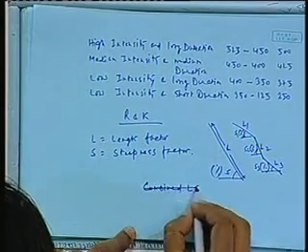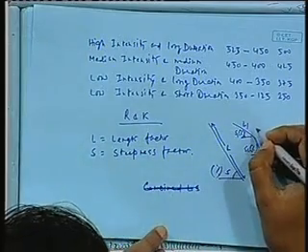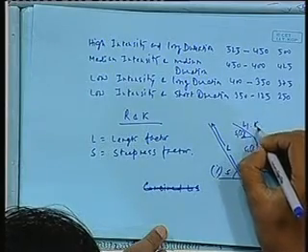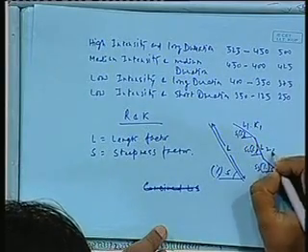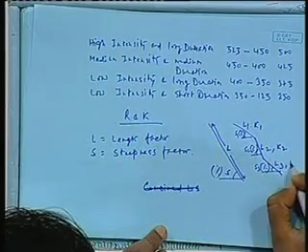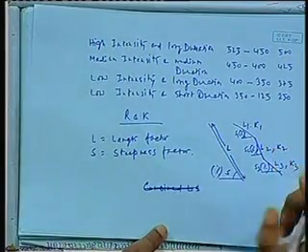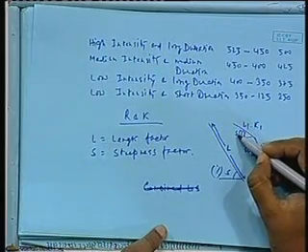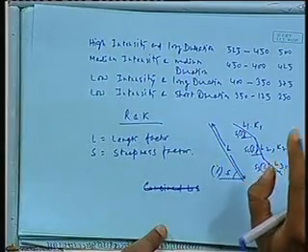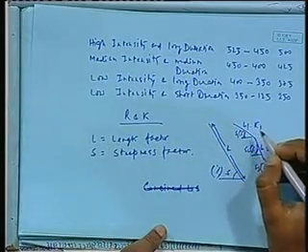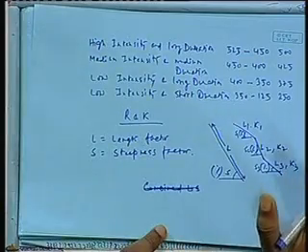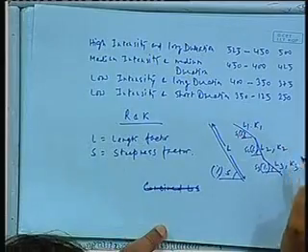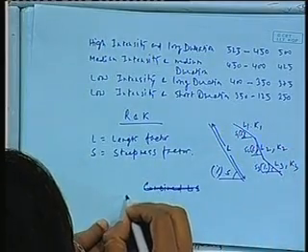In fact, it is not only the combined LS. Sometimes there is also the soil erodibility factor K1, with K2 and K3, depending on the different soil types. Remember this: L1 and S1 are the slope parameters, the length of the slope and the gradient of the slope. K1 is the soil erodibility factor depending on the soil structure, soil texture and permeability. So if these things are variable, in such cases we can find the combined